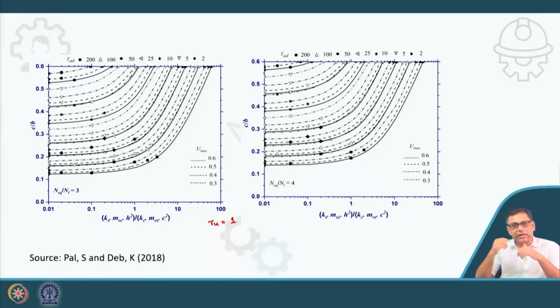So if your strength reduces, that means it is liquefaction when the ratio is 1, but if it is close to 1, still the strength will reduce. There is a generation of excess pore water pressure. So we will not allow that much pore water pressure to generate, so that the strength does not reduce to a level where the stability of the stone column will be disturbed.